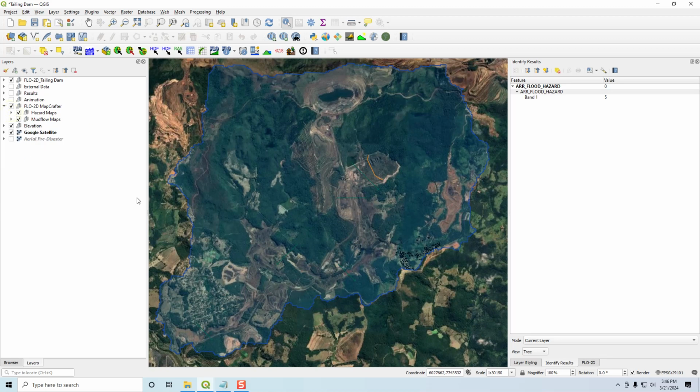And let's see, then that is MapCrafter. Then we're going to do floodplain cross sections. We have some floodplain cross sections set up in our model, and you can see them a little better if you plot them like this. Now, if you're on the new plugin, it's called version 1.0, and it's a lot shorter than this plugin, but you'll be able to load your project path where you ran your model, and click these individual lines and plot these cross sections. But with plugin 1.15, we do it a little bit differently.